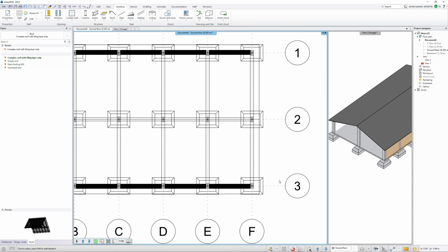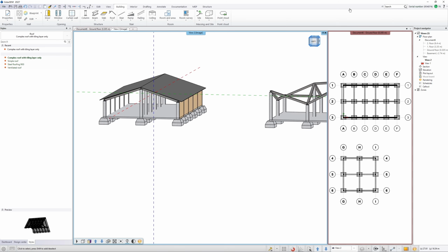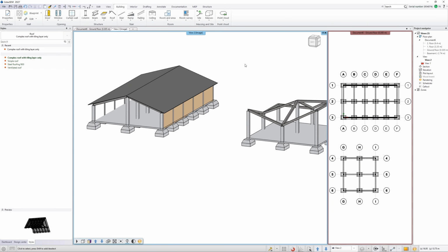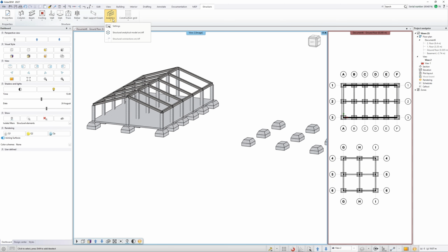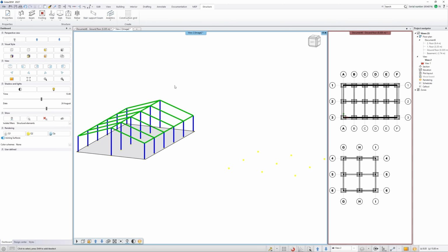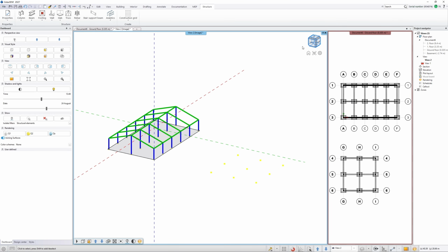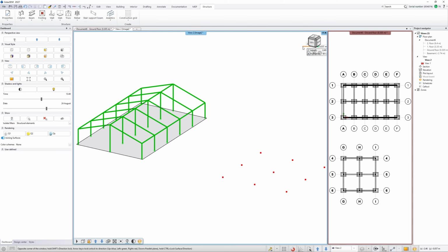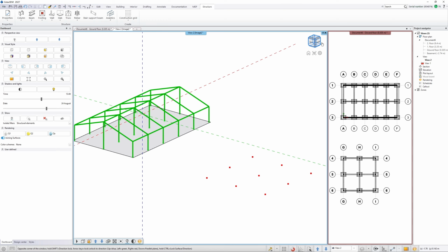The navigation cube remembers the last rotation center set, making it easy to view the completed building. On the Structure tab, you can use the Analytics command to check the status of the connections between structural elements. In Analytics mode, a schematic model appears, showing only the structural elements. If you want to view the connection between structural elements, you can also display the connection points. In this case, green dots indicate good connections and red dots indicate faulty ones.